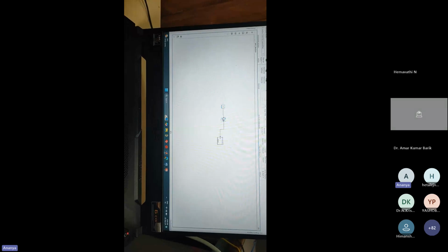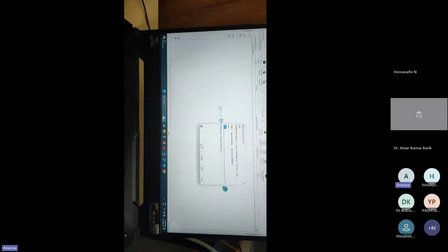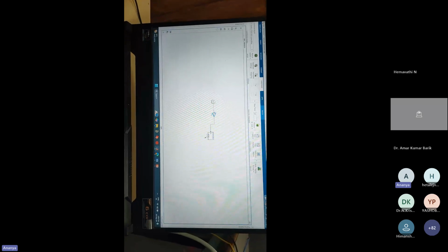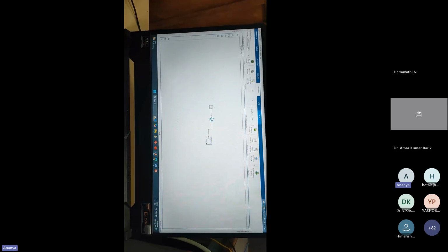Here we are driving this controller for 0.6 duty ratio at 25 kilohertz, that is 9999. As my friend Gaurav has already described in the previous session how to calculate this value for 25 kilohertz. And this is EPWM 5, that is pin 78. That's why we have connected to pin number 78.